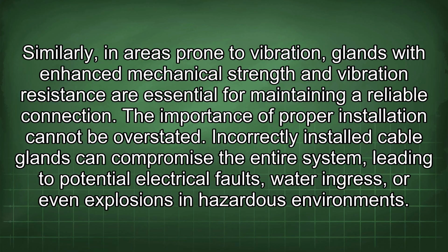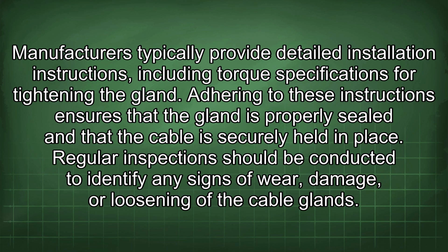Incorrectly installed cable glands can compromise the entire system, leading to potential electrical faults, water ingress, or even explosions in hazardous environments. Manufacturers typically provide detailed installation instructions, including torque specifications for tightening the gland. Adhering to these instructions ensures that the gland is properly sealed and that the cable is securely held in place.